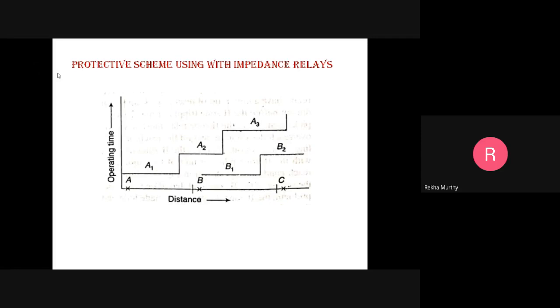It is a very high speed unit and is used for the primary protection of the protected line. This operation is very instantaneous, around 1 to 2 cycles. This unit is not set to protect the entire line, to avoid undesired tripping due to overreach. If the relay operates for a fault which is beyond the protected line, that phenomenon is called overreach. Overreach may occur mainly due to transients during fault conditions.